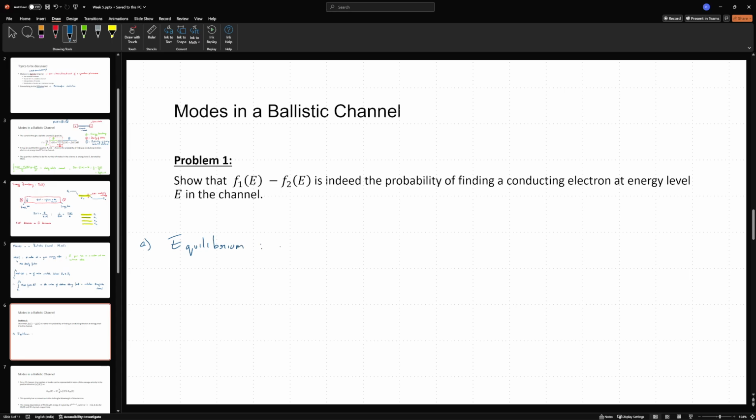So at equilibrium, V2 minus V1 is 0. No voltage is applied across the two terminals, and as a result, I is also equal to 0. Again, this is a concept that was invoked during the solution for the stored charge density of the channel. At equilibrium, there is one thing we definitely know: the Fermi levels of the three components of the device are going to be aligned.